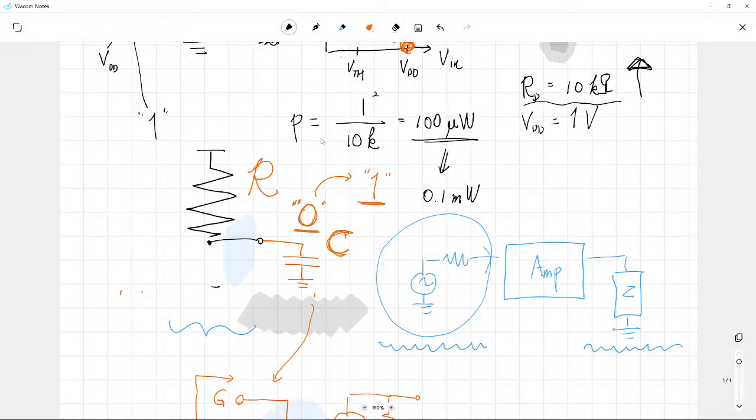Now this system can be viewed as this simple system. We have this serially connected R and C. Originally the value was 0, however it is abruptly changed to VDD. Then after a long time has passed, we eventually have VDD. That's true, but the time constant related with this transient is, well known as what?